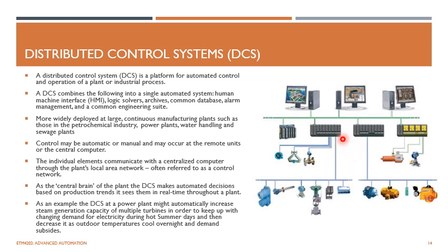Nowadays DCS is replaced by SCADA systems. The only advantage in DCS is you can write the program for each of the controllers from a centralized computer, and then upload or download the code to the controller.